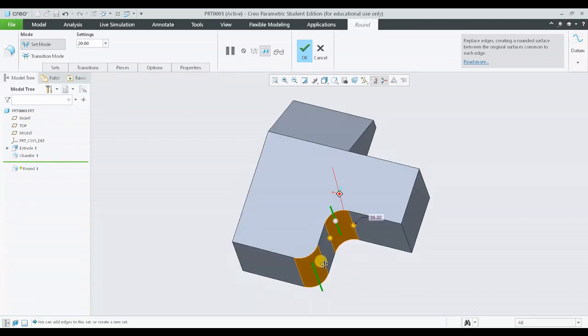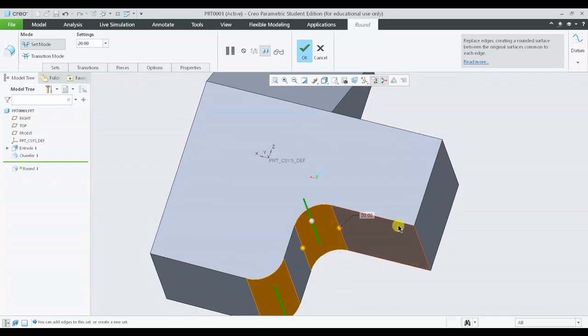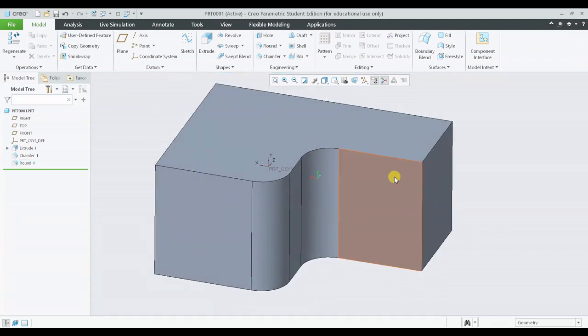These round features have converted all the edges into a single tangent line. Okay, so you can see the line is starting from this point. It takes a smoother turn tangentially, moving forward, again taking a turn and going till this point.